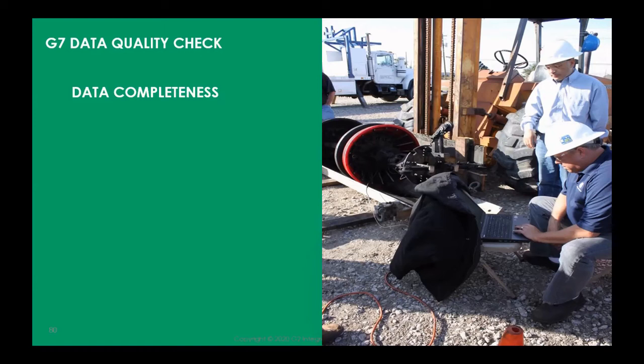In addition, you will have to look for striking signals in the data to confirm that the data meets basic quality requirements. So you will need to create and request a report from the inline inspection vendors that ensures that the data has been reviewed not only for data completeness, but also plausibility.